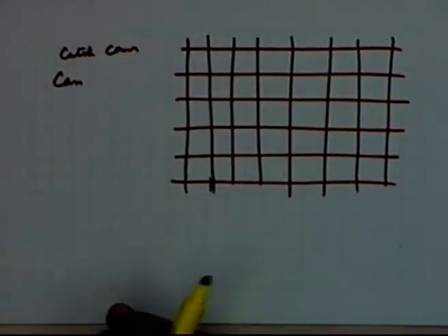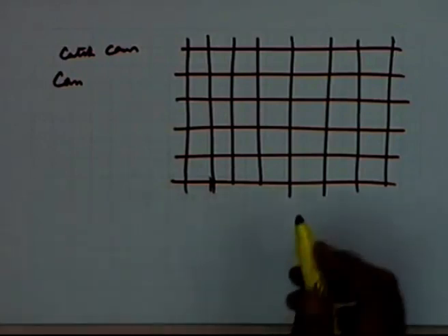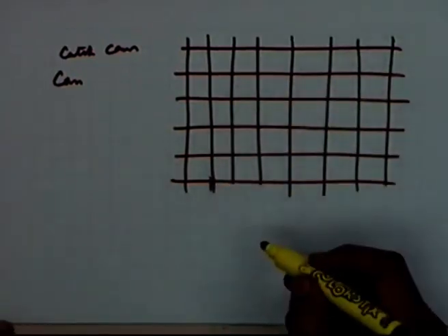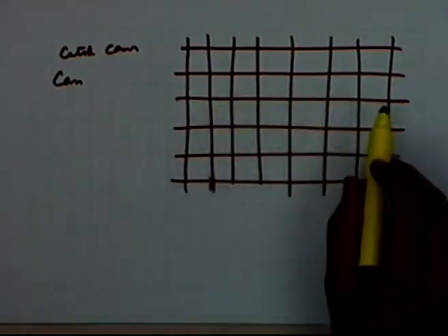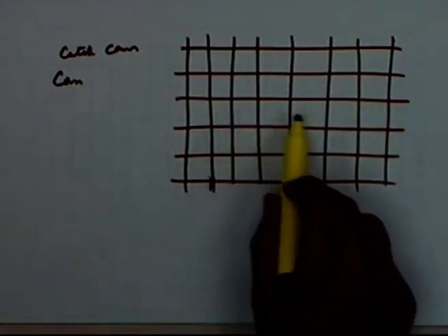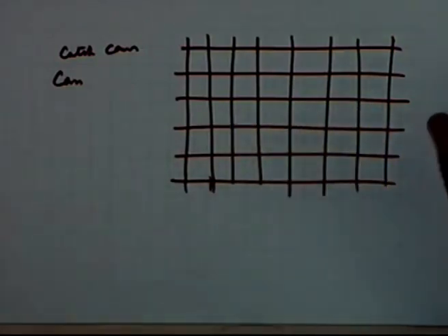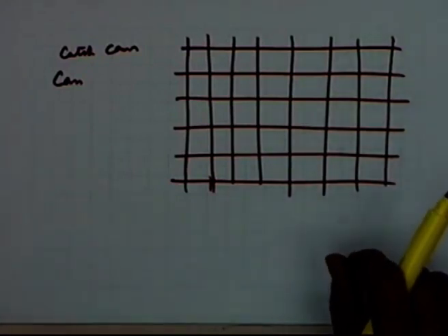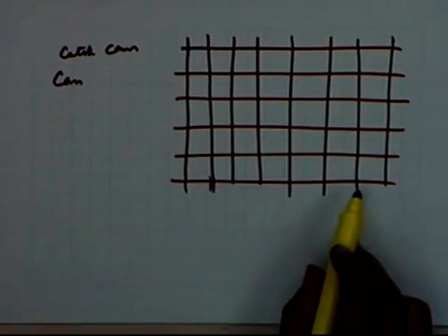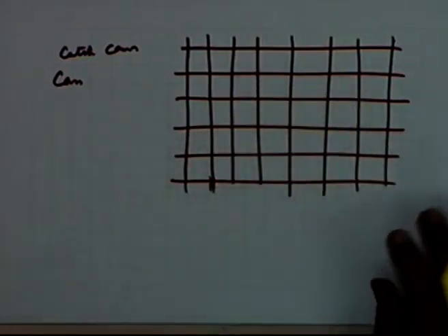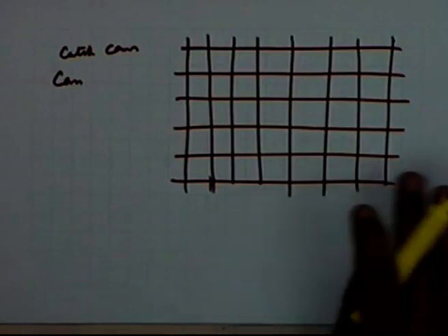These catch cans are small vessels installed at known points, and then you run the sprinkler for a specific duration, and then actually measure how much depth has been received or collected in those cans. So that is a simple way of finding out the distribution pattern, and that distribution pattern can be observed under different conditions, but the procedure remains the same.